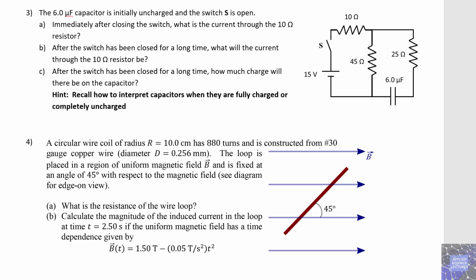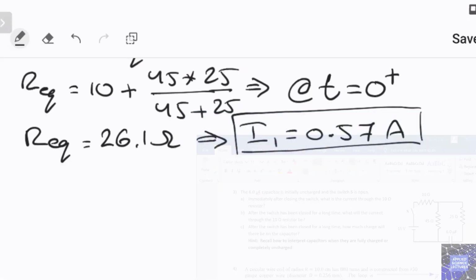So in this case, we're looking at the t equals to infinity case. So for the t equals to infinity, which is long time, I will redraw the circuit for the t infinity, and in this case the capacitor would have reached the steady state, would have been charged either to the maximum of the voltage or completely discharged, based on how this capacitor is connected in the circuit. So let's look at our circuit here.